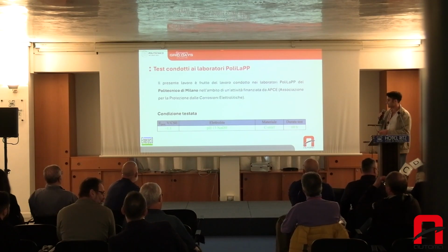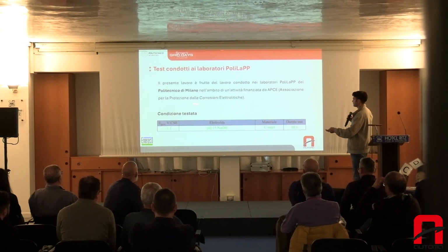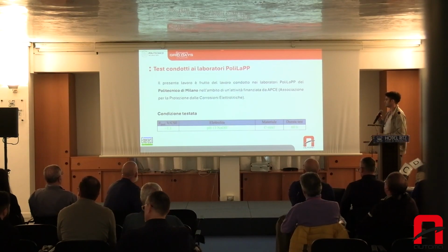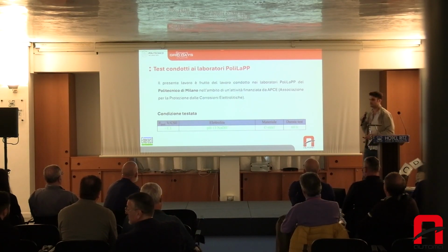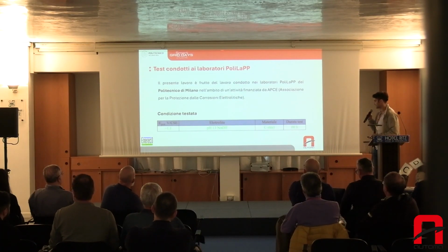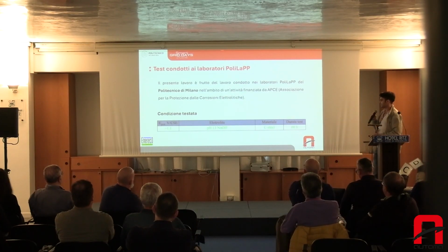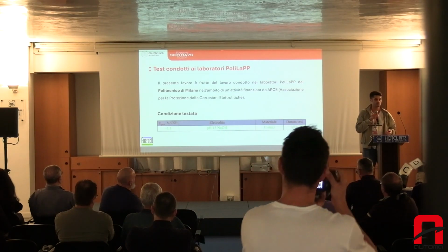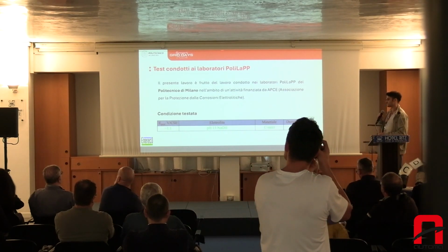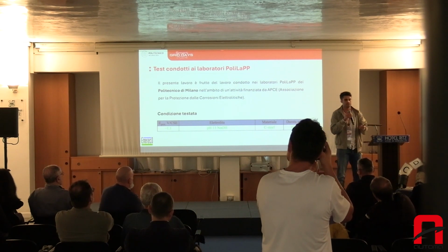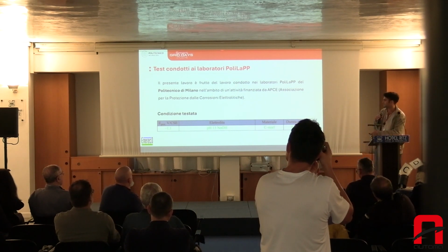To answer these questions, we started the system. So we polarized iron steel at pH 13, and I'll tell you why we started with an alkaline pH. We did a test of an electrochemical cell, in a slightly different condition compared to that of an acid pipe. It was a 60 hours test, which is quite a limited duration.